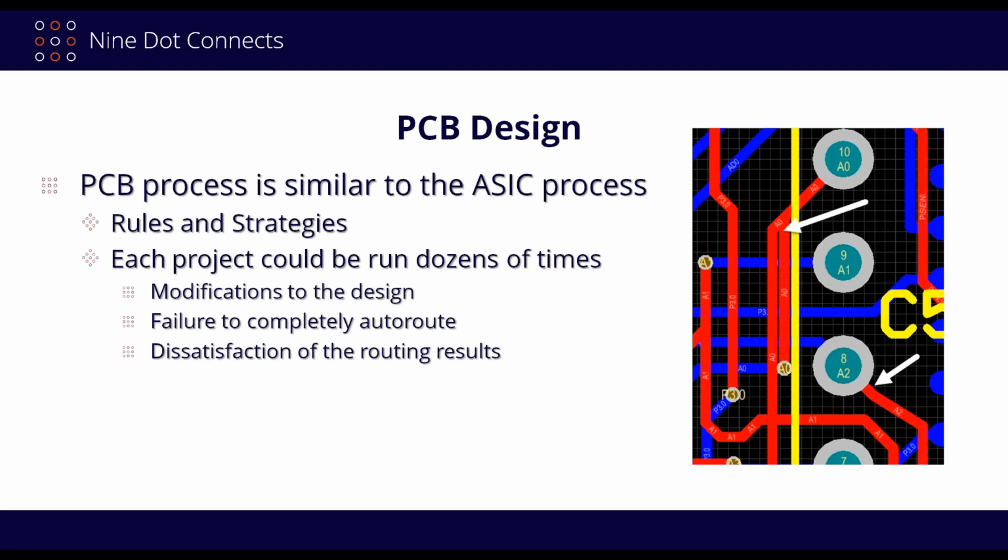And so as a result of this, I should have an expectation of having to run this several times until I get something that's very optimal. Okay. Cleanup is still very, very necessary. You're going to just see that. You're going to see some really weird and unusual routes, and that's just the byproduct of the router.